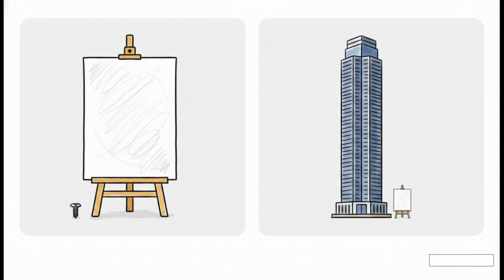So the crucial point is this. Enlarged scales lead with the larger number, while reduced scales lead with the 1. Simple as that. It's this beautiful binary system. That mathematical formatting tells you in a split second whether the drawing or the actual object is bigger. And because it's so universally standardized, a global workforce will literally never misread a technical document.